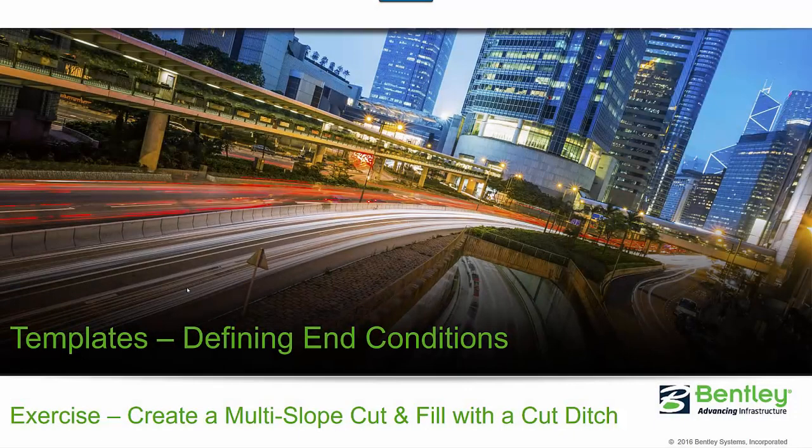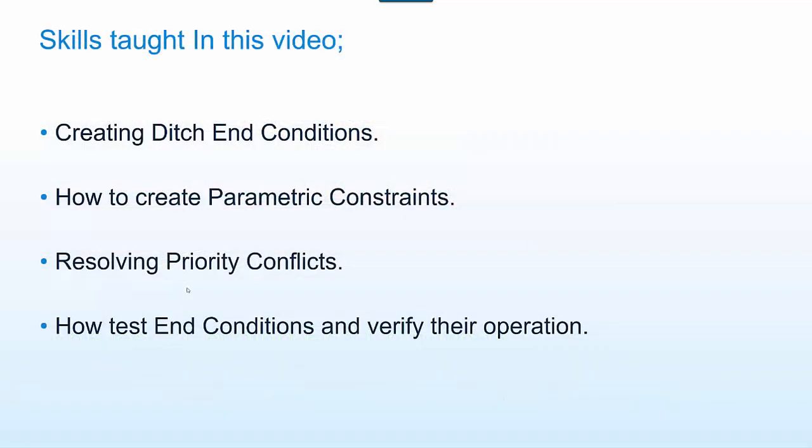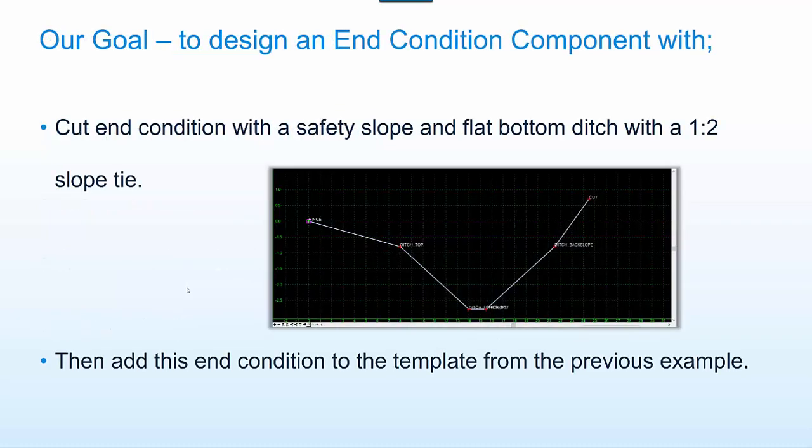Hello and welcome to the exercise Create a multi-slope cut and fill with a cut ditch. In this video we're going to create ditch end conditions. We're going to show you how to create parametric constraints, resolve priority conflicts, and finally how to test those end conditions and verify their operation.